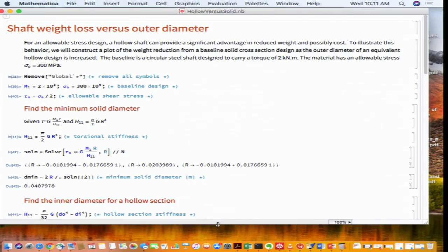And the reason for that is when we took an incremental element and applied the Taylor series expansion on this element, saying that my shear force is V here and V plus dV over dx1 there, now you cannot expand the Taylor series across this spring. So that's the reason we break it.